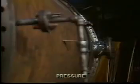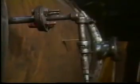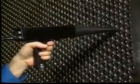The pressure method is conducted by first sealing up outlets to prevent the gas from escaping and connecting house air to the inlet. The system is then pressurized. Test the system as previously demonstrated. Listen for the characteristic rushing sound of a leak with the ultraprobe scanning module.